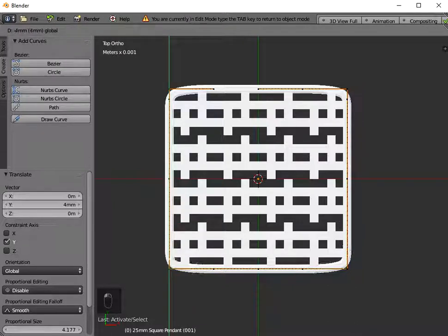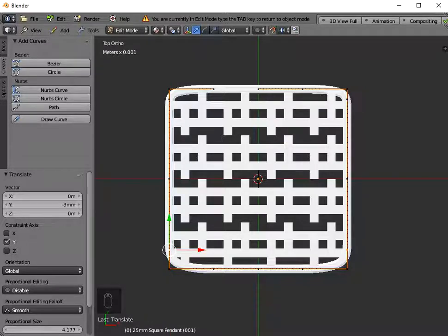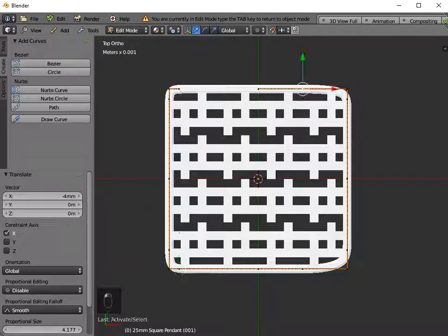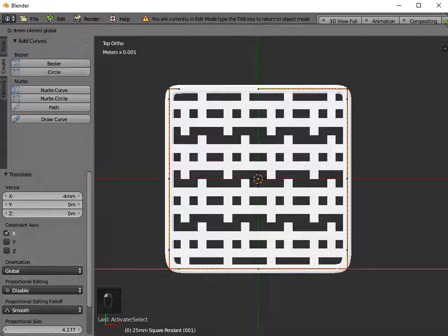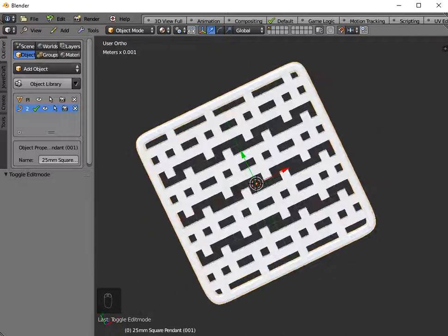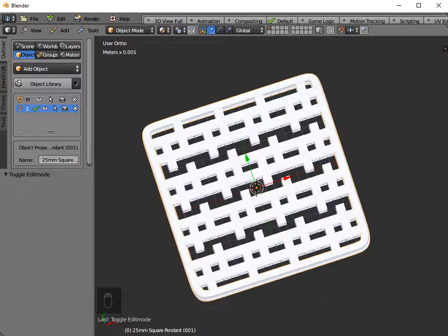Come down and then go back one, so it's all nice and even. And do the same with the control point at the top there and the bottom. Come out and come back one. And the same with the control points there. Go out. So by doing that, I've eliminated that bit of the mesh sticking out there.